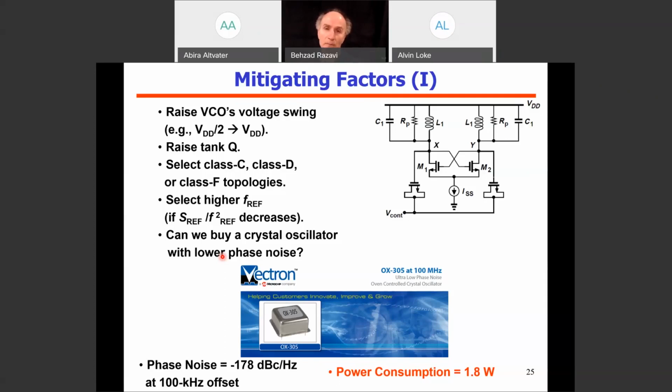Another question. Have you studied how different system architectures might mitigate the need for low phase noise, such as multi-tone approaches for wireline or multi-band ADC architectures? Yes, good question. In terms of multi-tone signaling, actually one of my students published a paper many years ago, and it turned out to be more serious in terms of phase noise requirements because we have multiple narrowband spectra next to each other in the case of multi-tone signaling, and then if there's any overlap between them, that causes problems.